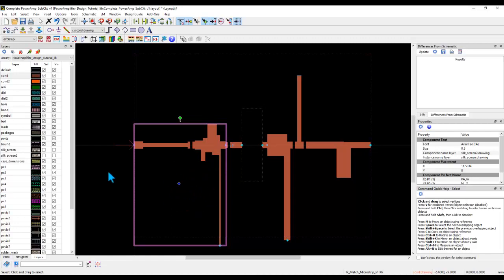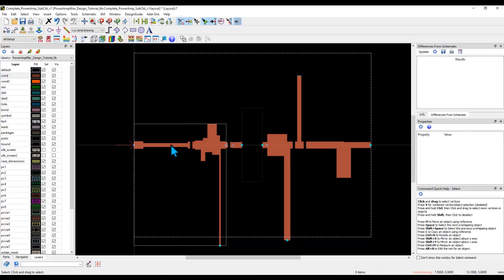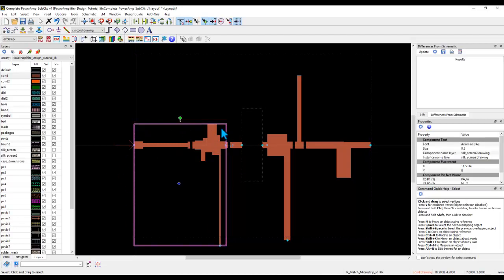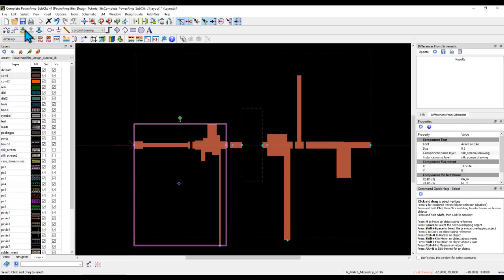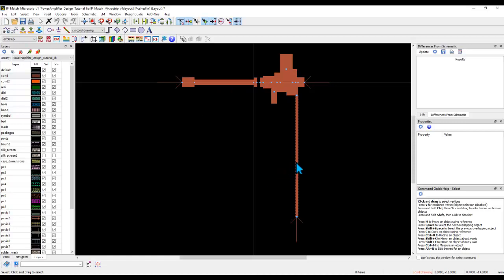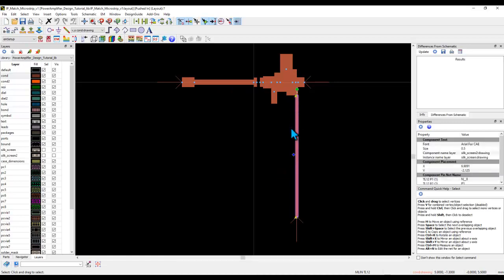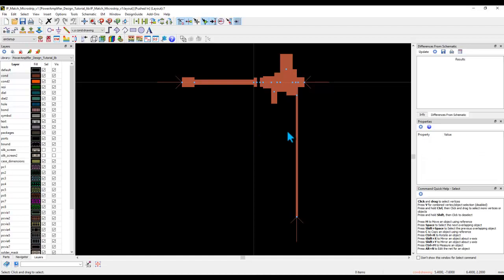Now when you do that, you have a couple of options to take care of this. One is, remember, this is a hierarchical sub-circuit of input and this is a hierarchical sub-circuit of output matching. So I can select the hierarchy and push inside the hierarchy by using that button. And now here I can modify this length or this line and I can rotate it the way I want. That's option number one. And how you rotate this line is very, very simple. So I'm going to show you both the variants. I'm going to modify the input transmission line inside the input matching network.